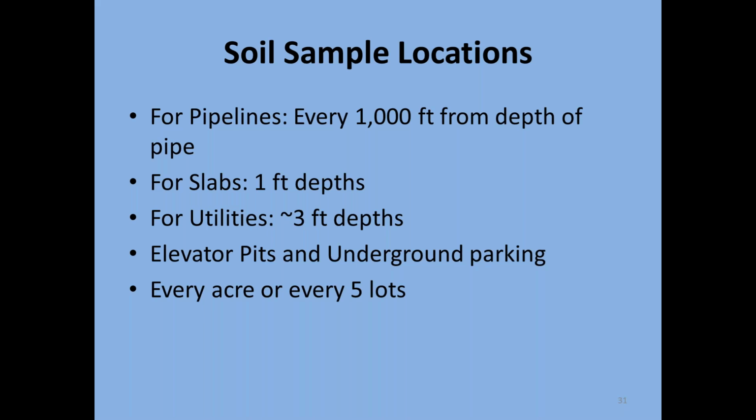Then typically, for soil samples, for slabs, 1 foot depths are good enough. For utilities, they're typically around 3 feet deep. And then for elevator pits and underground parking, you want to get a couple of samples from every 5 or 10 feet, depending how deep this whole thing goes. And like I said, collect from every acre or every 5 lots. Back when I was at Schiff, I think most of our clients were collecting every single lot and testing every single lot. So that would be great too.